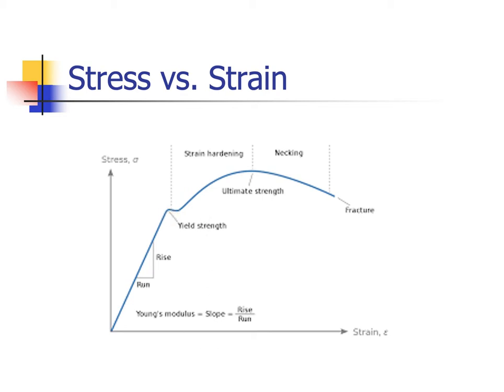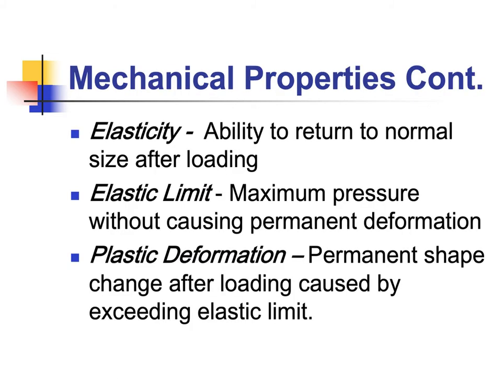Okay. So, elasticity is the ability to return to its normal size after loading. In other words, that first part of the diagram is the elastic portion where it's proportional. And essentially that's what a spring is. You use a spring in that elastic range. If you ever did the spring constant in a physics class or something like that, you already did this. You actually already did Young's modulus. You just didn't know what you were doing with it.